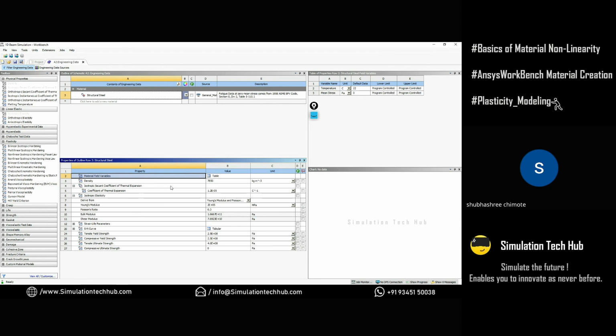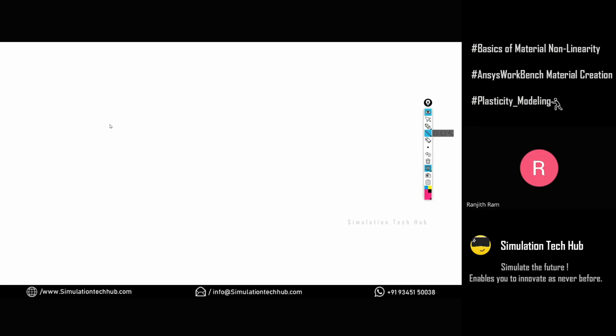How it works is that it's a derivative, I mean the normal tangential modulus. We get it out of the stress-strain curve. If I want to draw a typical stress-strain curve, this is the x-axis and this is the y-axis. Here I have strain, and here I have the stress. When we start to apply the load, the stress-strain relationship will go in this way.